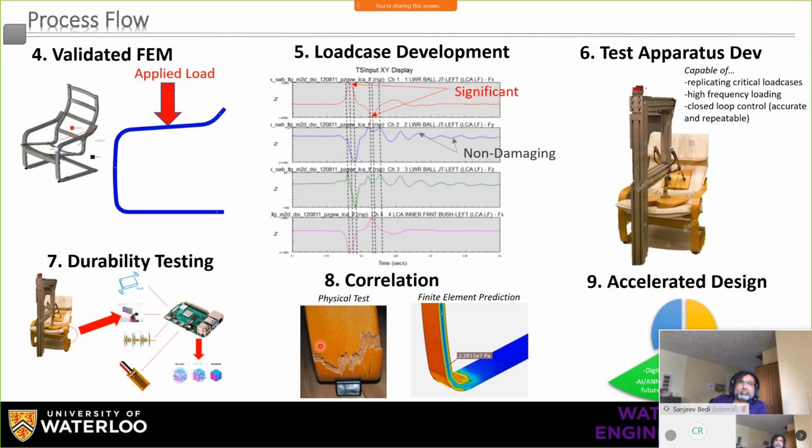So we're going to use the test data to improve the Ansys model, or the predictive model, or the digital twin, the result from that. And this is another iteration loop to do the finalized correlation, because now we're correlating it not to the actual test data. It's going to be the accelerated durability test. Okay.